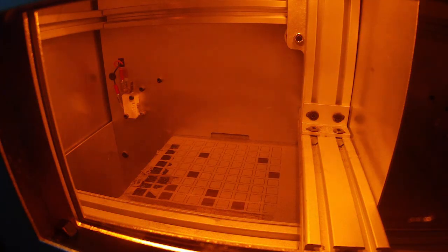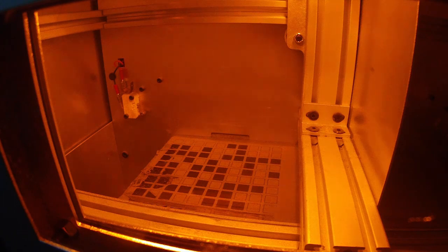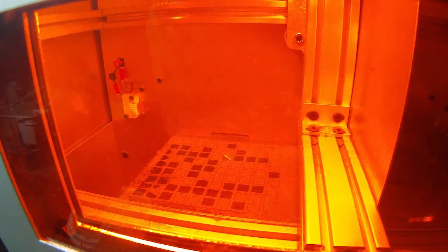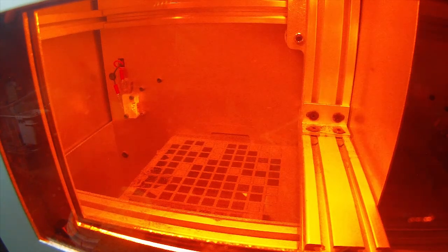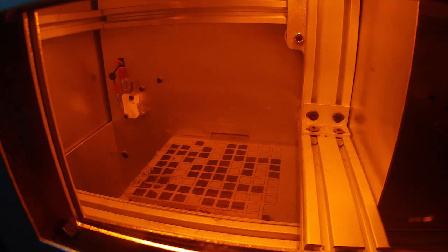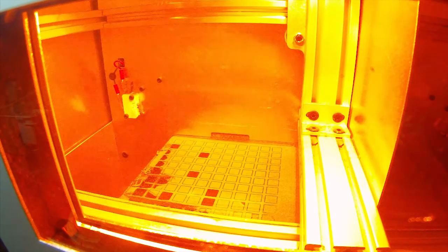And it doesn't use a lot of powder. This thing's only, I think, 3 millimeters or 4 millimeters thick, each of the squares. So a tiny bit of powder, put it in the machine, test it out and see what you can get out of it. And then just keep increasing your temperatures to find where you can get your optimized volume. And you figure out where you can get a good square, something around an 11 centimeter square, and then when you pull it out later on, wish I had video of this, you examine the center squares and make sure that none of them are fused together, because if they're fused together, you went too hot. So 174 is going to be too hot.